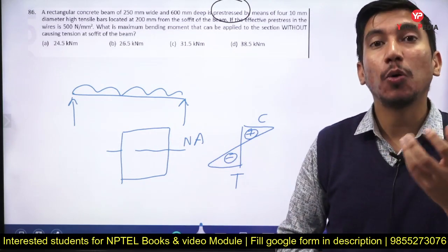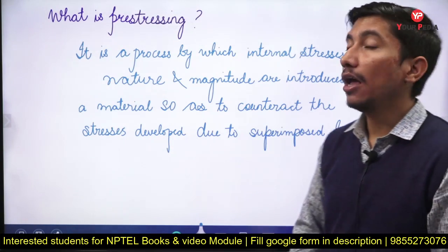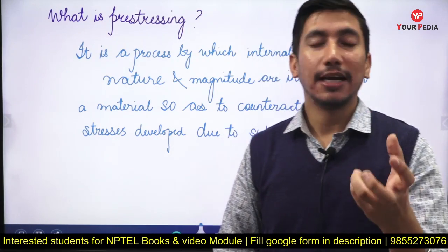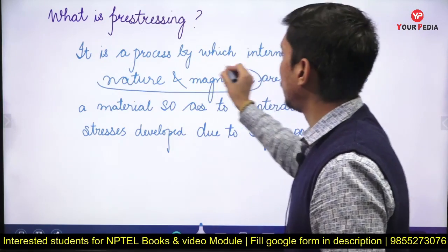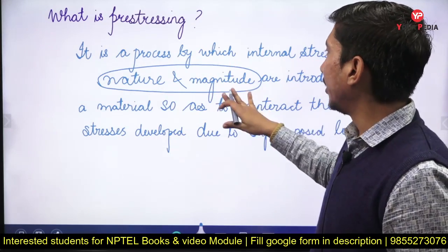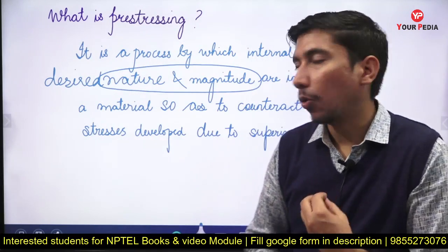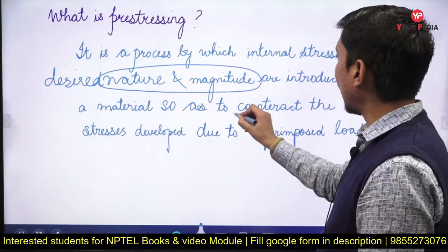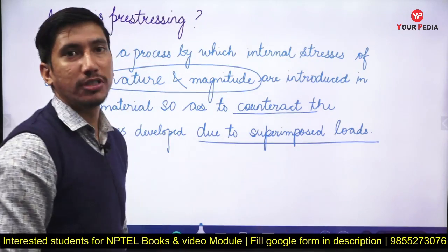So let me first tell you what is pre-stressing, what is this concept. Pre-stressing is the process of introducing internal stresses of desired nature and magnitude. Now this line is very important, I'll explain why. We have to introduce stresses of desired nature, according to what we want, and desired magnitude in a material so as to counteract the stresses developed due to the superimposed loads. Now this is very important.